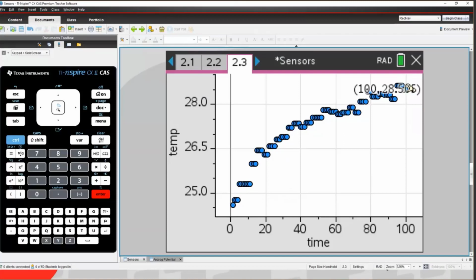And it's also important, you can see here, it toggles a little bit, 28.6, 28.5. Now I was holding on to it the whole time, and yet it jumps about. So it gives you an idea of error margin. So we're seeing about a 0.1 degree difference it can jump around on. So just remember that when you're writing up an experiment that might be using this stuff, there's about a 0.1 degree variation. But if you think back to an old analog one, or particularly the old alcohol-filled ones, the one with a red bar on it, it's pretty hard to read 0.1 of a degree sensitivity. So I'm reasonably happy with that. So that's our temperature sensor.